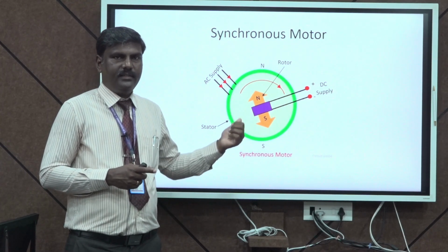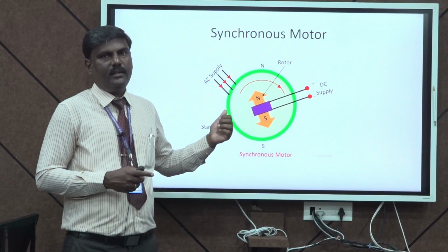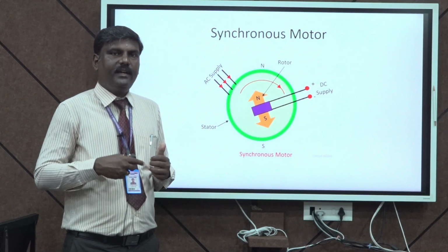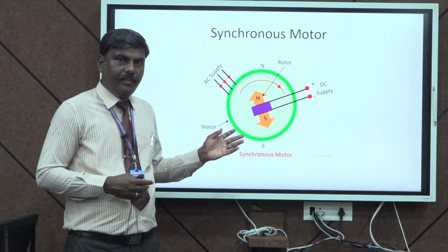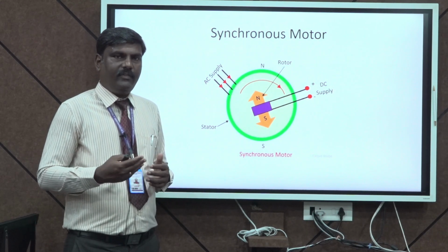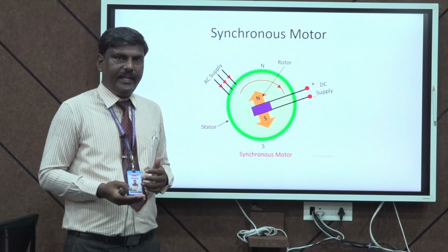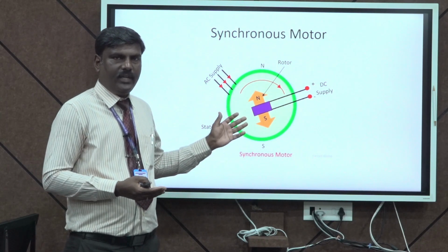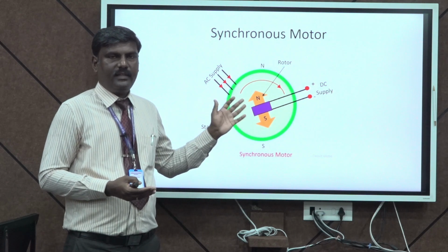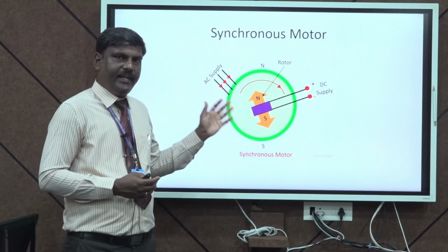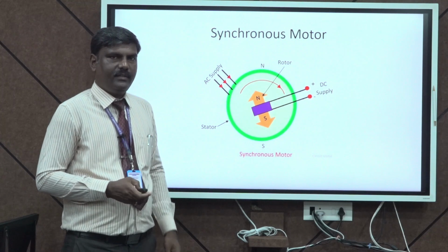In many places, this synchronous motor is used as a synchronous condenser. It can operate in all the power factor modes, that is lagging, unity as well as leading. So this motor can be used as a synchronous condenser for compensating the reactive power in industries.